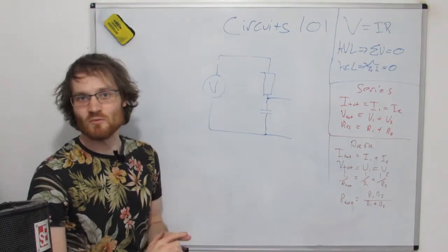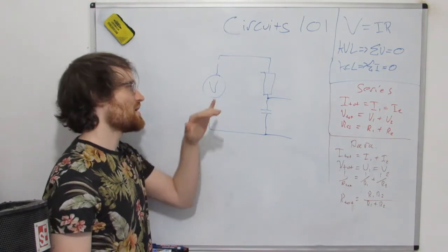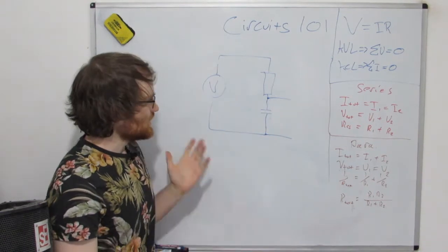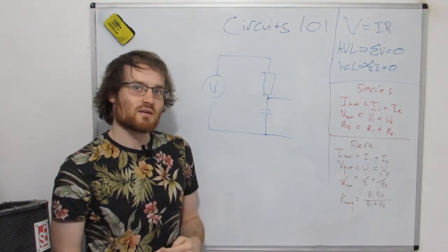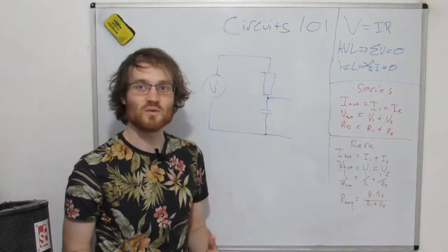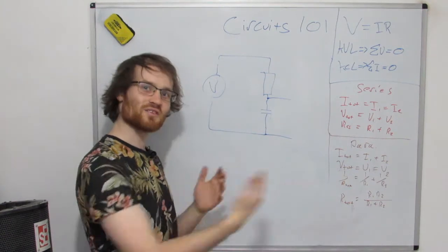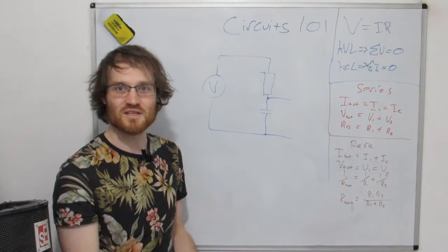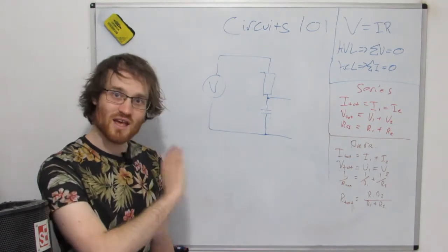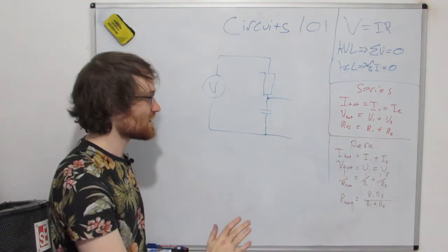So, impedance, what is it? Well, to talk about impedance, let's think about what a resistance is. The resistance is the amount of opposition an electrical component gives to any given voltage. So a voltage is a force, the resistance is kind of opposing that force, and the current is what is allowed to flow by that interplay. So resistors don't care about what's coming in. If it's AC, DC, whatever, they don't mind.